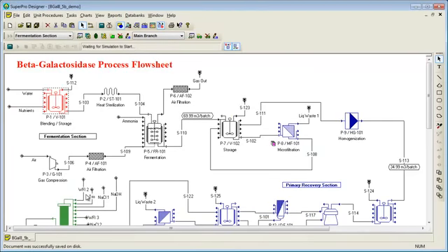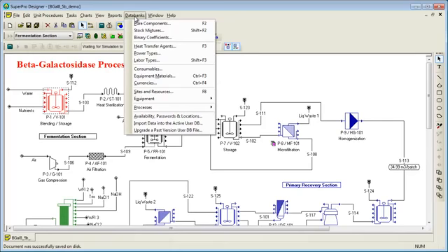Note that if you frequently use specific mixtures of materials in your processes, you can create pre-specified stock mixtures from your pure components. This will make it easier to initialize input streams and track process inputs. After the materials and mixtures have been specified, they are available to be used within the operations and streams of the flowsheet. Other process resources can be specified through the Databanks menu.